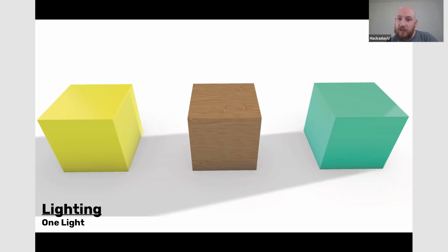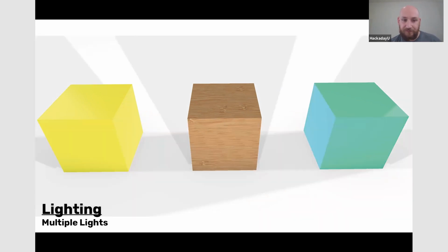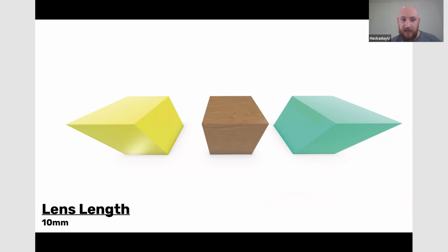Then lighting, we can turn on. I'll show you lights when we open Rhino, which then shadows will appear in your render view, which normally there wouldn't be shadows. And you can set environment settings, set what location this model is in the world, what day it is, what time it is, and the shadows will sort of match that timing. And then there's just multiple lights with multiple shadows.